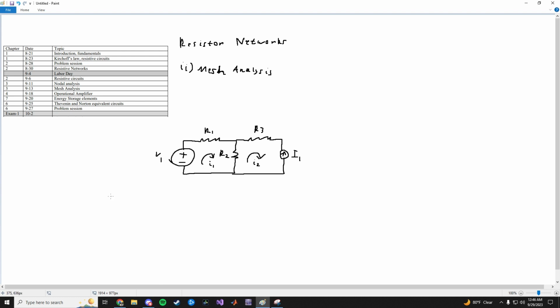So remember, the mesh analysis, the basis is now the KVL, the Kirchhoff's voltage law, which states the voltage drops across every component in a closed loop has to equal 0. So given my arrow, you want to follow the arrow just like nodal analysis. So I'll start from here and then follow the arrow, which is going that way, and I'll add the voltages up.